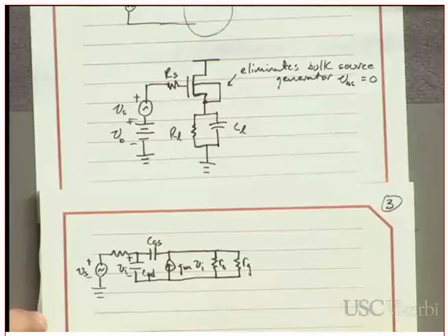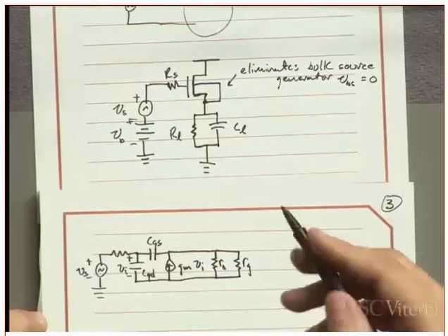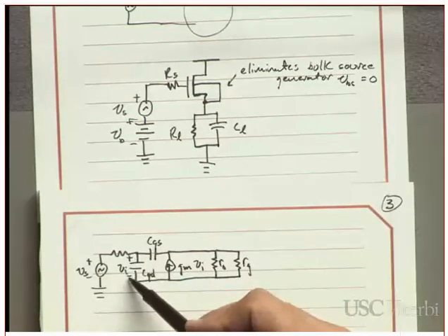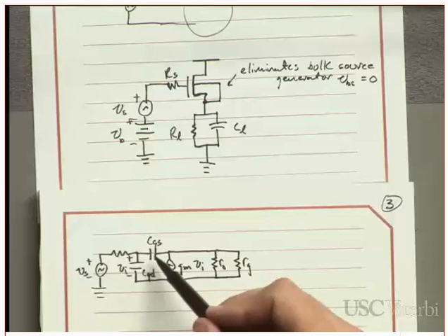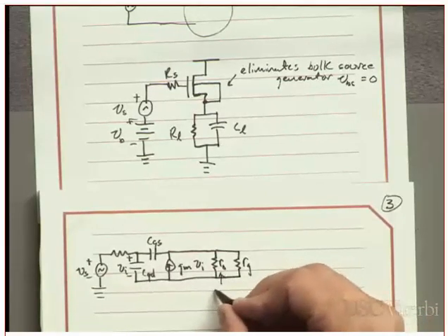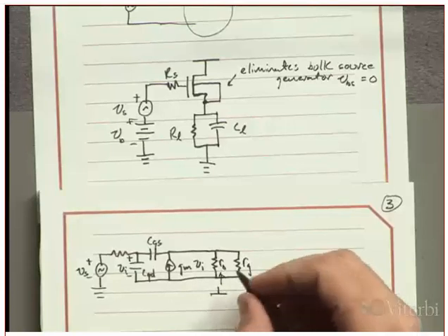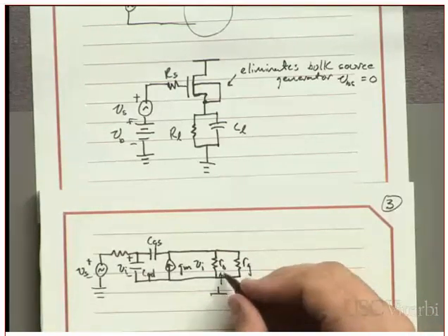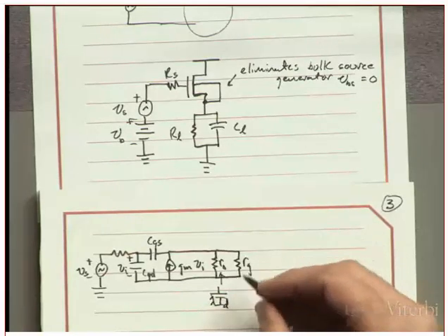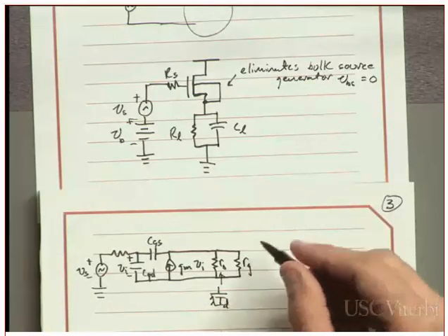This one I should have eliminated, I believe, because of the bulk to source voltage generator. Oh, no. I'm sorry. This one came from the fact that I moved this voltage control to CGD instead of CGS, if you guys remember. Sorry. This one we often write as 1 over GO, but the resistance itself is 1 over lambda ID, where ID is the Q point current.